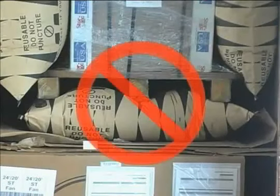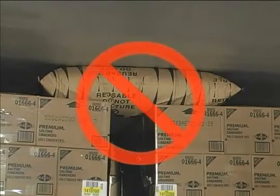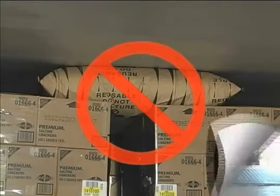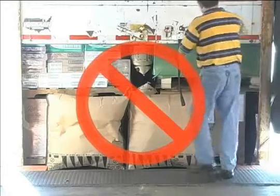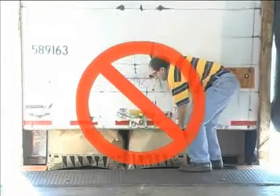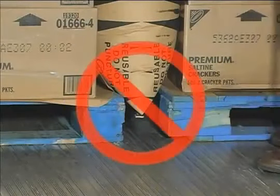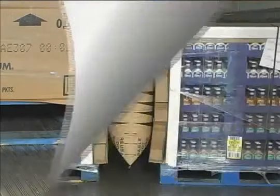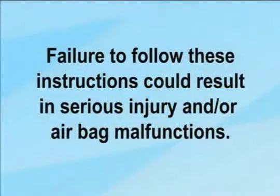Never use airbags as leveling devices. Never position airbags between the top of the load and the trailer roof. Never place airbags between the load and the trailer door. Never position airbags near pinch points. Never allow airbags to touch the ground or the pallet. Never let an airbag get wet. Failure to follow these instructions could result in serious injury and/or airbag malfunction.